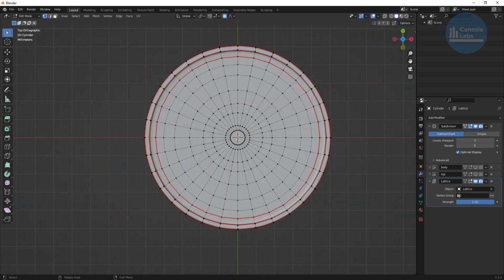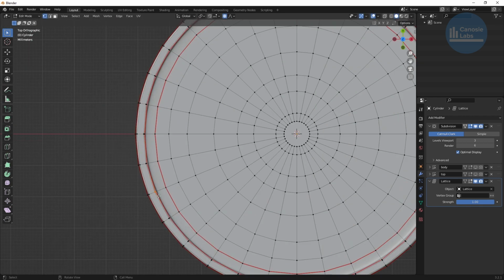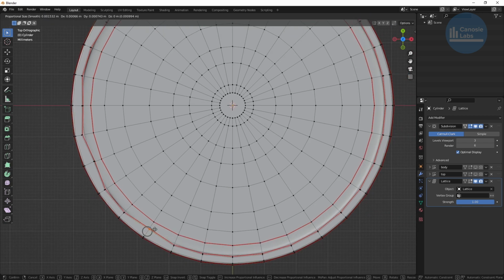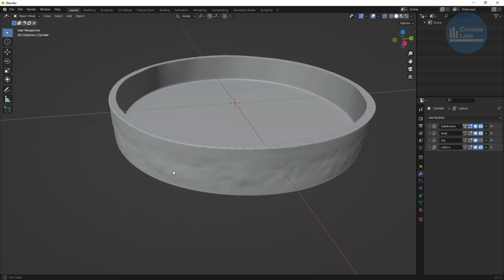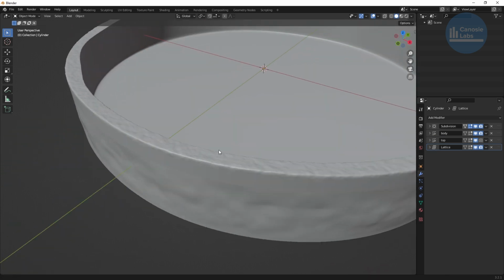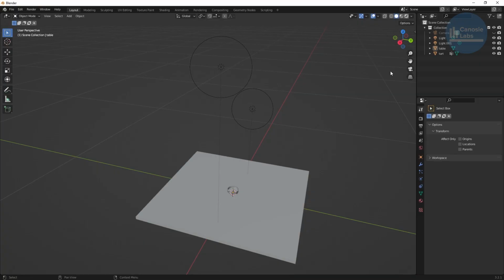Don't go overboard. Also, the tart thickness shouldn't be perfectly uniform in width. I couldn't get the desired results using the lattice modifier or noise-based displacements, so I had to manually adjust some vertices to add some distortions to the thickness. Again, it doesn't look right if it's too perfect. That's about it. The mesh of the tart isn't too complicated. Instead, we'll be adding detail via more noise-based displacements using the shader editor.